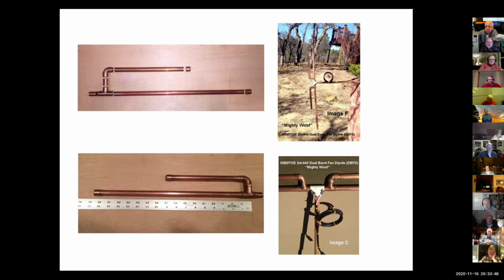One of the things that Bob was thinking about, and I've heard from other people too, that makes this antenna so nice is that it's very broad-banded, like you saw on those graphs. The reason is because it's a very thick element. It's a half-inch thick element, and that seems to expand the band characteristics to make it very broad.